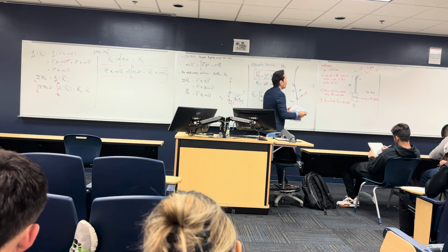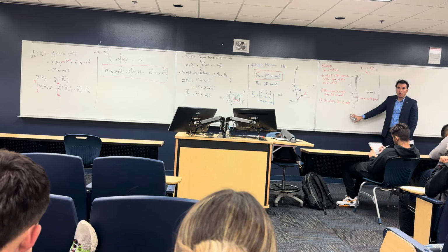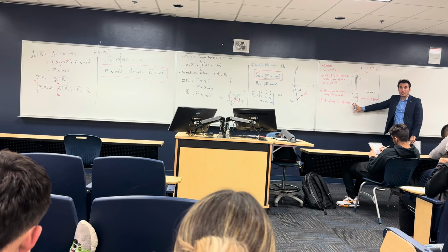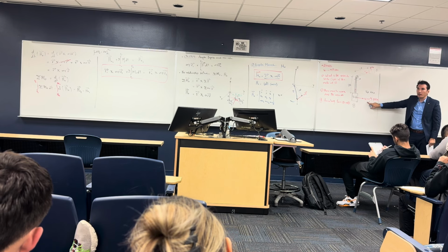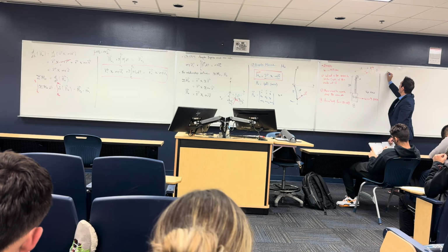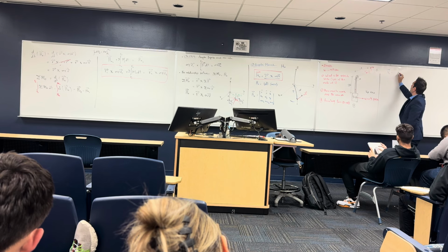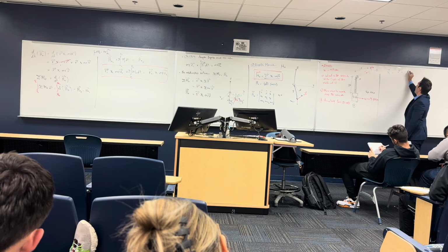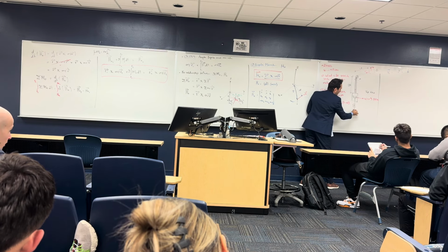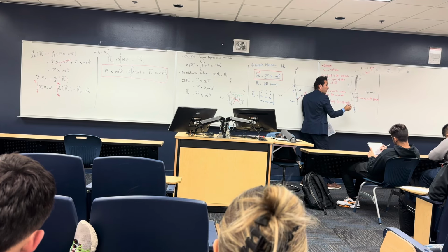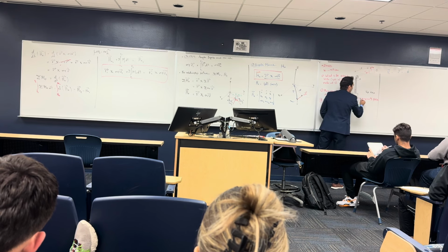The first thing, we need to put this velocity in vectors. So let's find the initial velocity at 1. At 1, this body was in a steady state. This arm wasn't shrinking, but it has an initial velocity of 0.5 feet per second. So the velocity vector V1, the total velocity, has a component in the r hat and another component in the theta hat. If you guys remember, r is always in the arm direction. This is r. And theta is perpendicular to r in the direction of increasing theta. So theta is this way, right?